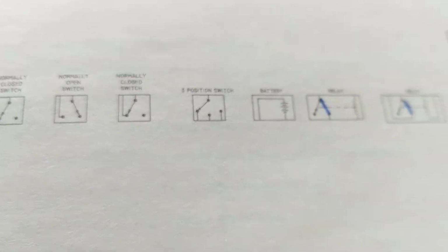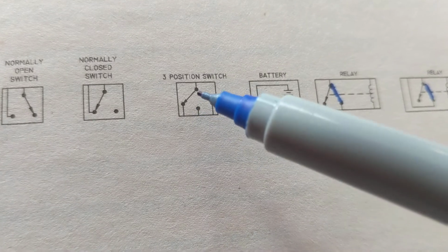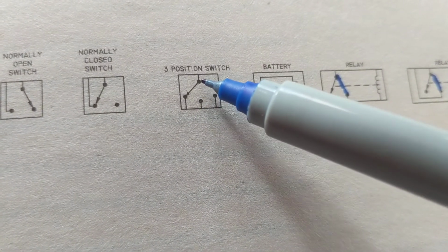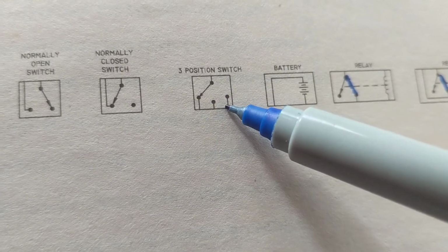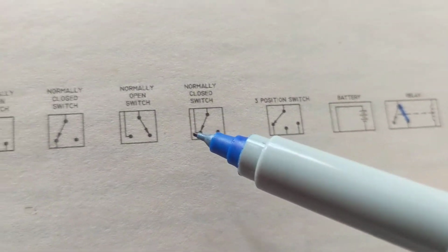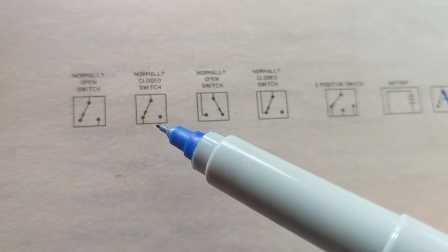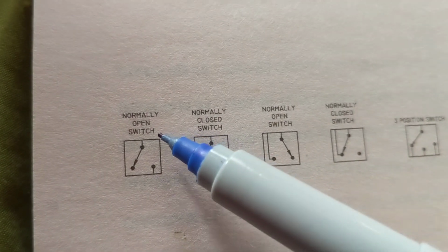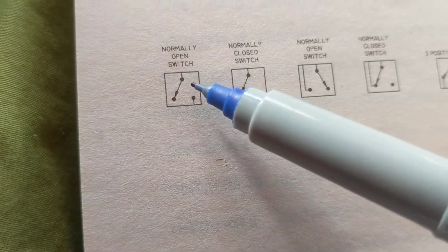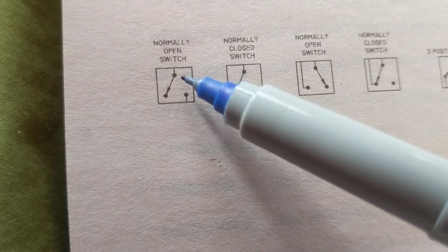Now, again, ignition switch or any switch, whenever you flip the switch, you're either going to connect it to this one, or to this one. See the lines? Now, this is the very important part to understand switches. At rest, this is normally open. And what I mean by normally open, it means this is the default.